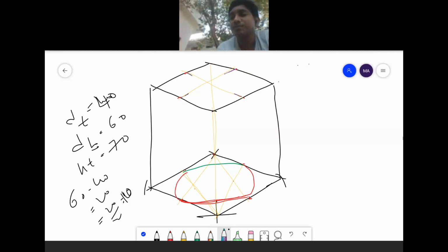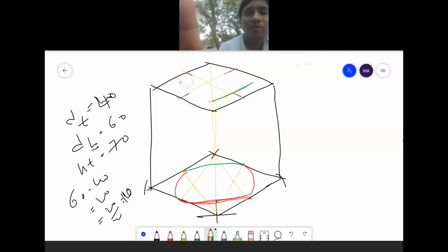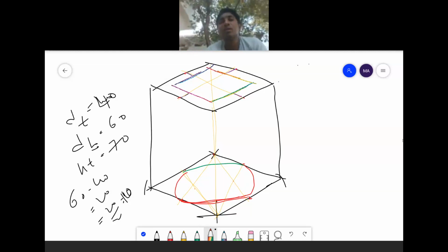I will reduce 10 mm here. After that, I will draw the lines here. I am using some other pen to draw the lines. I am drawing a horizontal line from here, and a joining line from here. I will form a square of 40 mm with this.